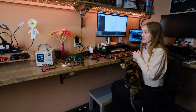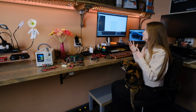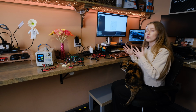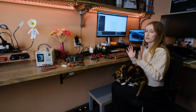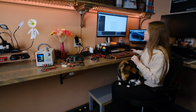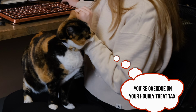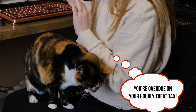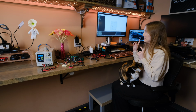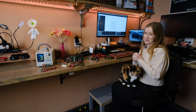Personally, I found, at least in this version of DASYLab, and maybe it's just my particular installation and the fact that my Windows 10 is a little bit out of date, I do feel like there's some sort of memory leak issue somewhere, which I have found is alleviated a little bit when I specify a block size and don't let it specify the block size automatically as it needs it. Again, that's just a quirk with this specific version of DASYLab. I do expect that to be updated in the future.